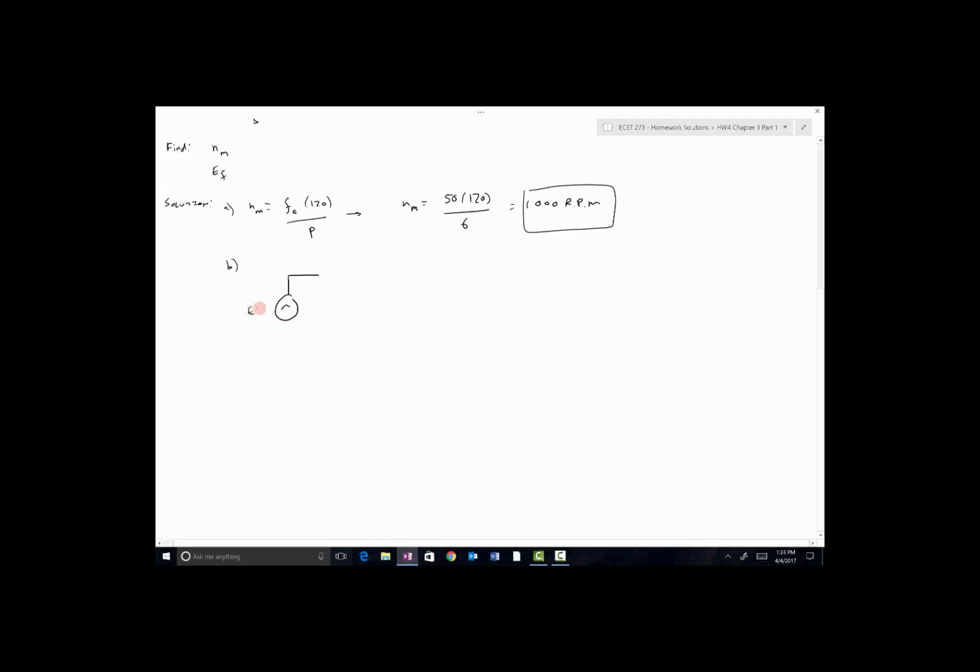We've got the excitation voltage E sub F that is induced in the armature coil. We then have the armature resistance and the synchronous reactance of the armature X sub S. The output voltage after the voltage drop associated with the current flow through those two devices is called the terminal voltage V sub T, and that then serves this load Z sub L.